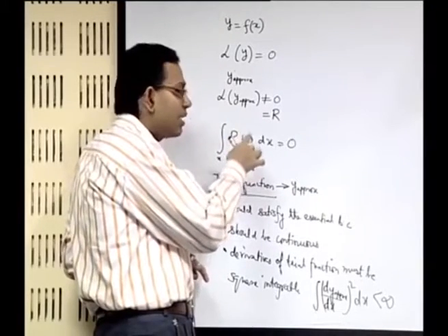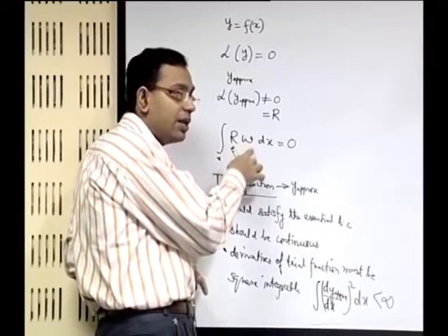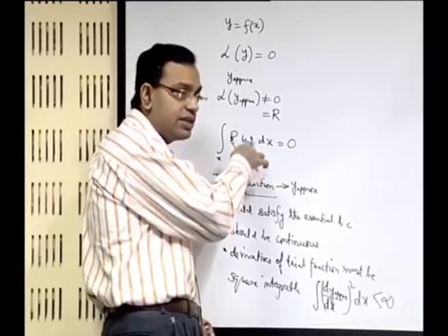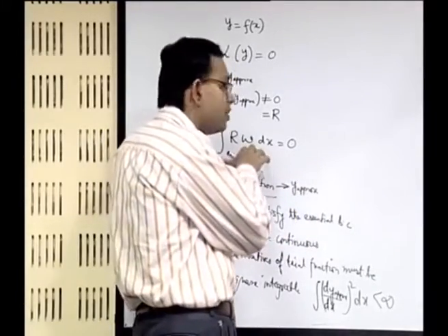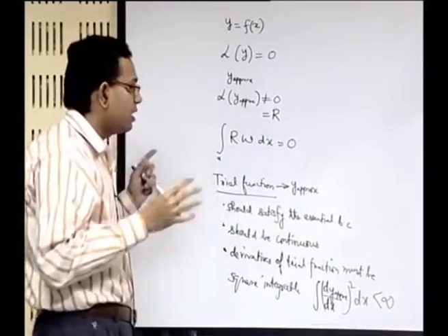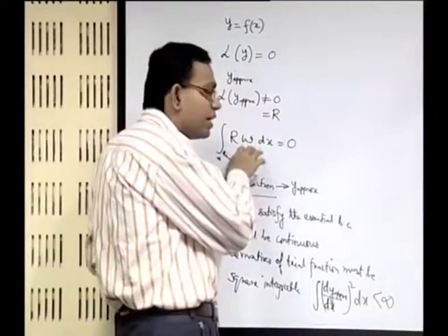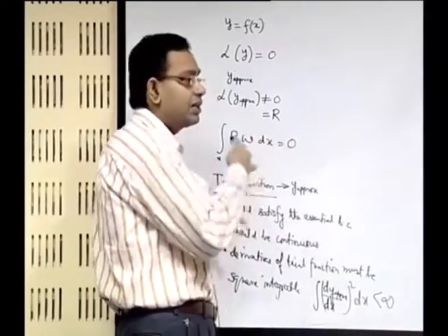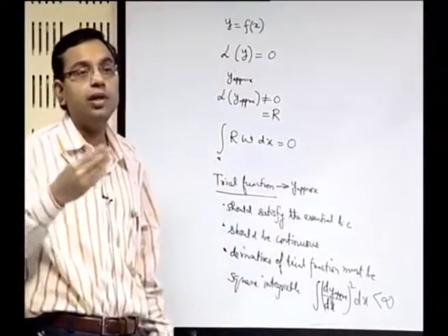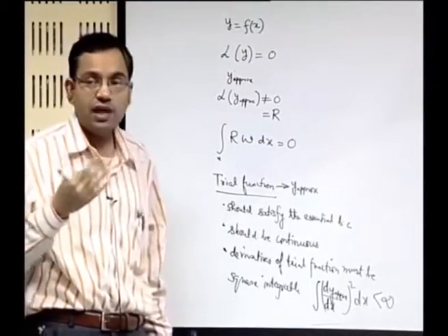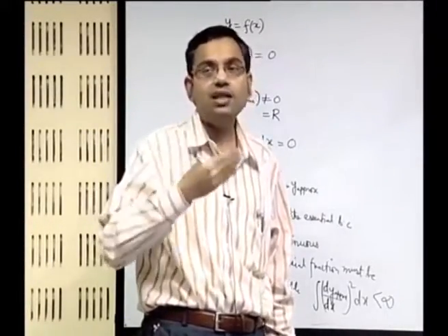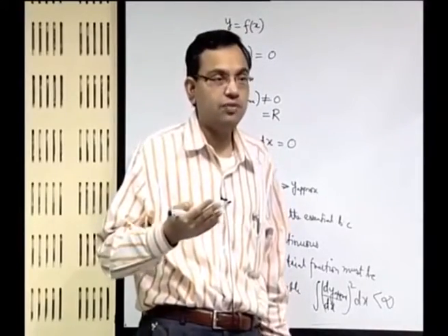The weighting function has a similar meaning as that of a variation, but it does not mean that you have to go through the roots of variational formulation. We will see that you can have any arbitrary choice of the weighting function, of course consistent with certain constraints. But the whole understanding is that for a second order problem also, if you do not go through the variational formulation, you will require a second order derivative continuity if you do not reduce the continuity requirement through integration by parts. So, the variational formulation is sometimes called weak formulation, because you weaken the requirement of the order of the continuity of the approximating function.